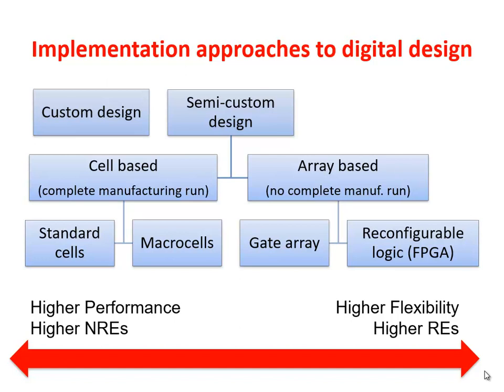Okay? And then in addition to that, if you want reprogrammability, then you have some overhead also in terms of circuits, and then on space on silicon. So you have larger areas and therefore higher recurring expenses. Okay, and if you remember, the recurring expenses increase super linearly with respect to the area. So you have a significant increase in that direction.